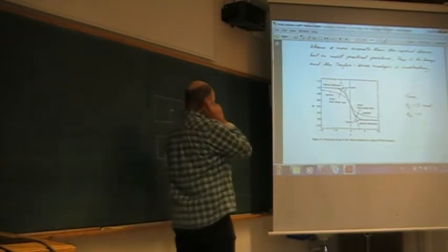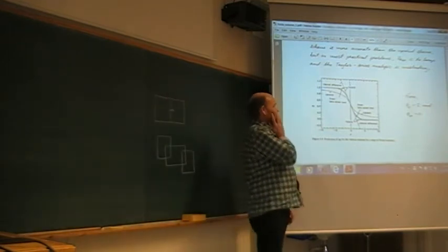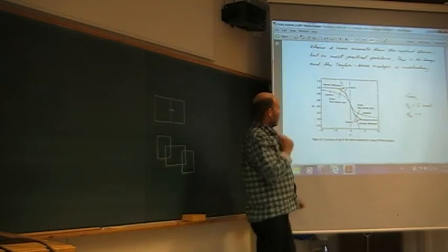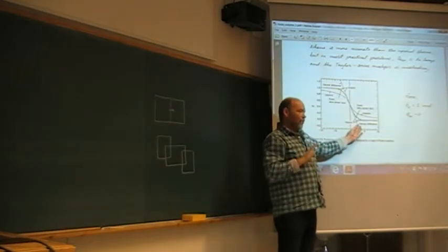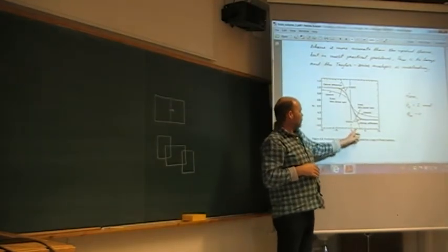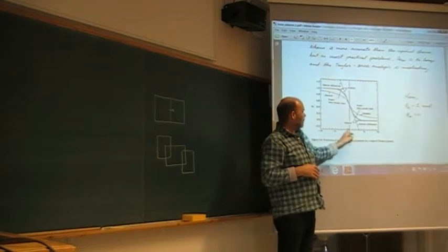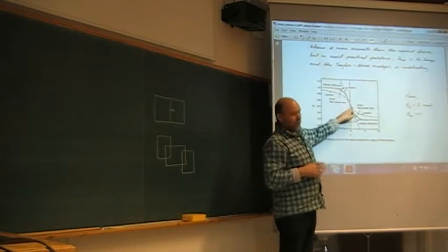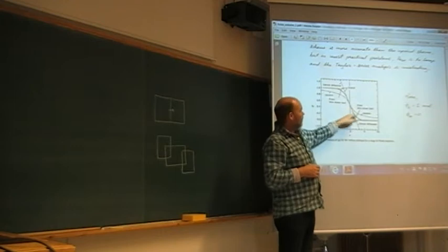But say, as a conclusion, the central difference is sort of the best if you are able to use it, if you can keep your cell Reynolds number small. Then it is the most accurate, quite clearly.